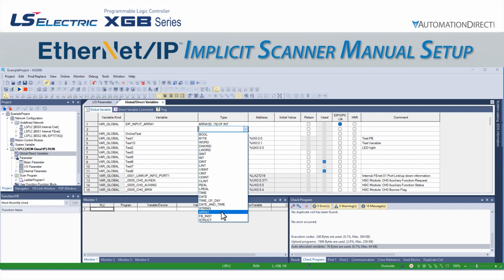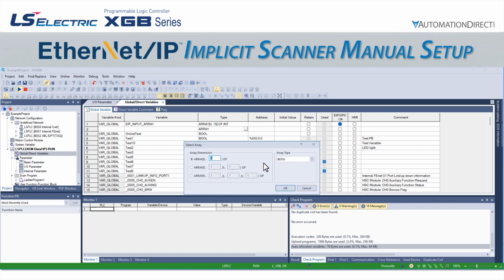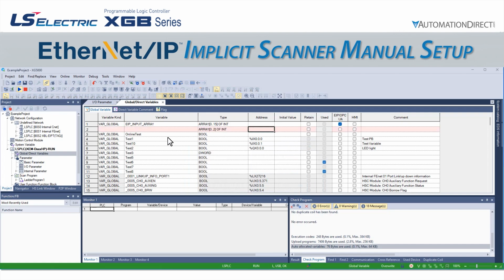Now we do the same for our output array. We will make it a 1D array of 0 to 2 elements and int type. This will again correspond to 6 bytes of information. This one we will name EIP_output_array. We will make it a global variable with a checkbox for EIP OPC UA as well.